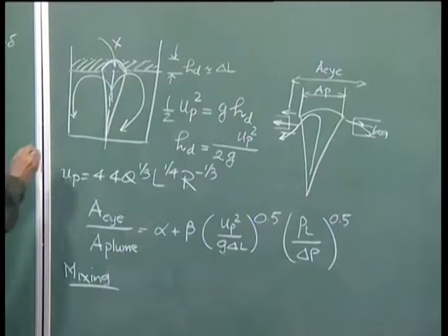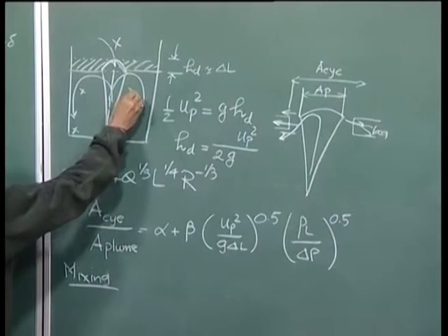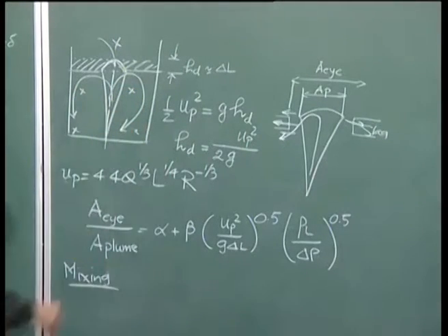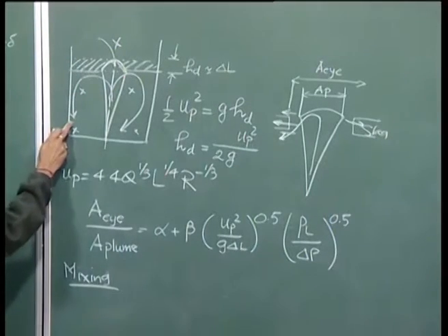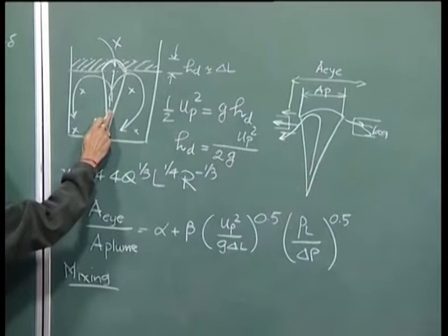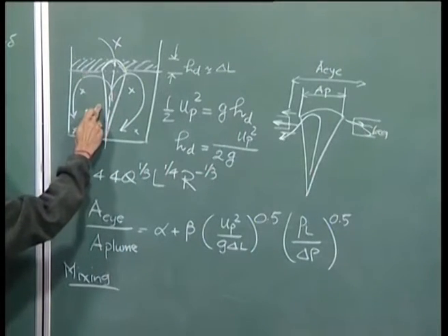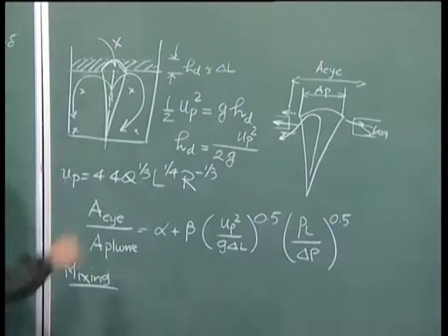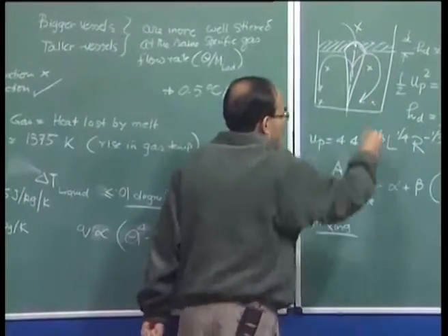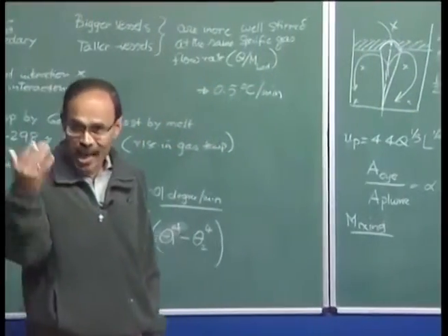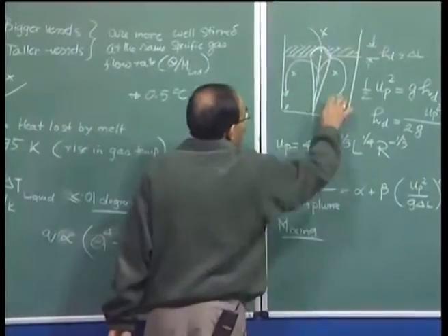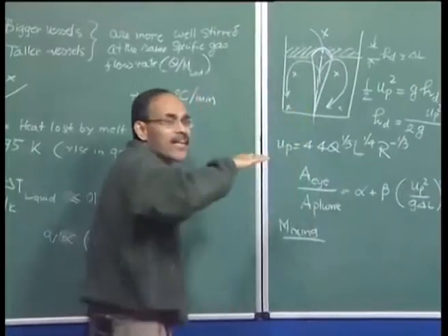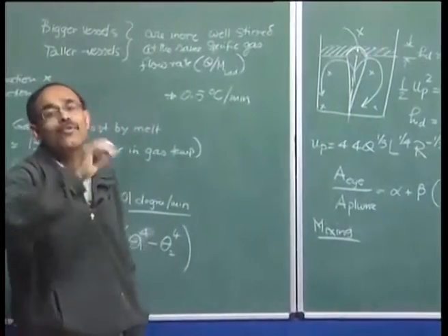We also may have different temperatures in different regions, and we may do gas stirring. For example, if there is more heat loss to the surface, the temperature here is going to be cooler than the temperature at the center, and as a result we may have some thermal stratification in the system. We can remove that thermal stratification by gas stirring, which does some amount of thermal mixing. Similarly, we may have some inclusion differential counts in the system, and gas stirring is going to give rise to a uniform inclusion distribution.